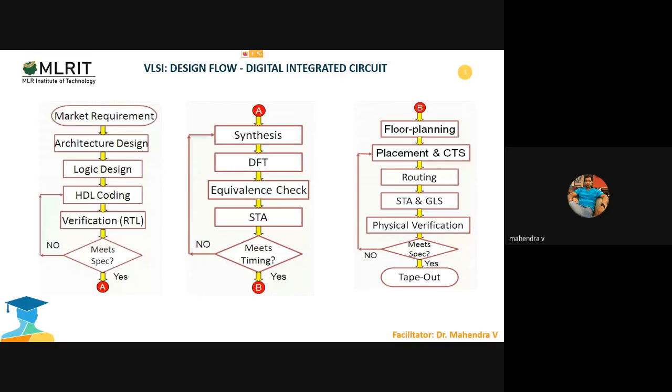During the static analysis, we can apply some timing procedures. After that, we can see whether this design is meeting the requirements or not. If it is not meeting the requirements, then we go back to the synthesis process, where we have to set the optimization level. Based on the optimization level, these timing requirements will vary. If it is meeting the timing requirements that we captured during the market requirement stage, then the design is good to go to the next level, where we can verify the physical feasibility of the design.